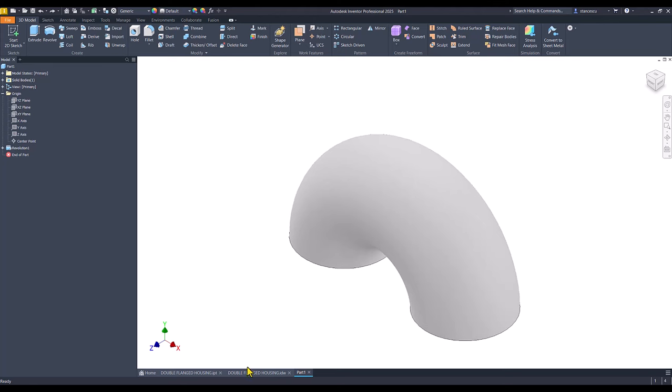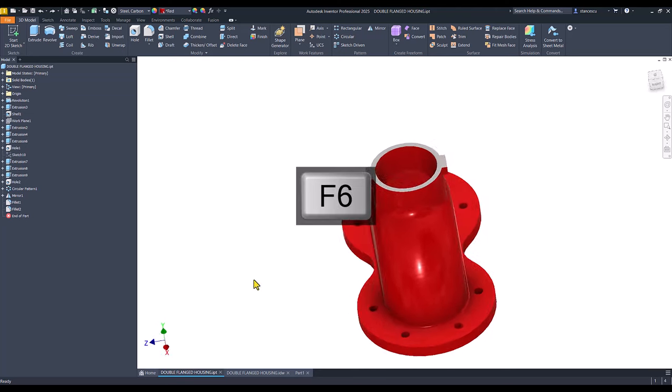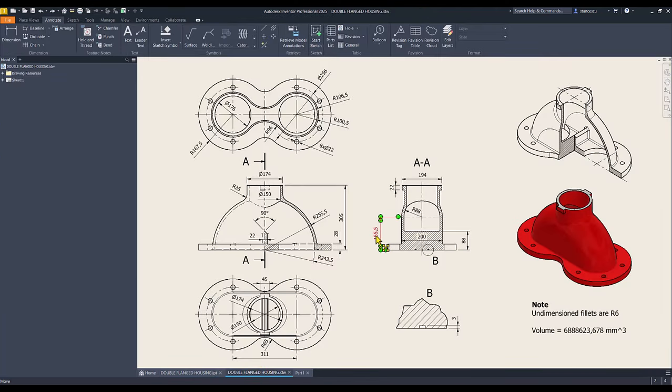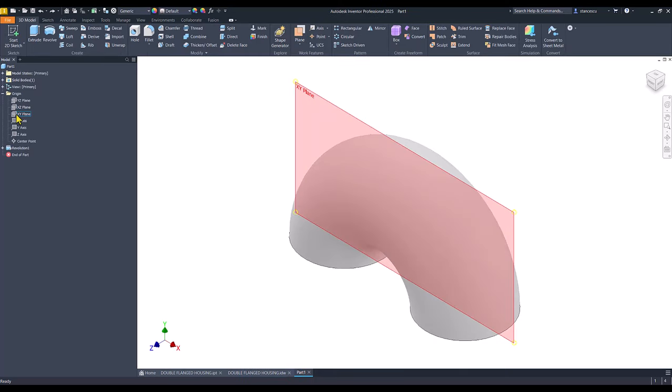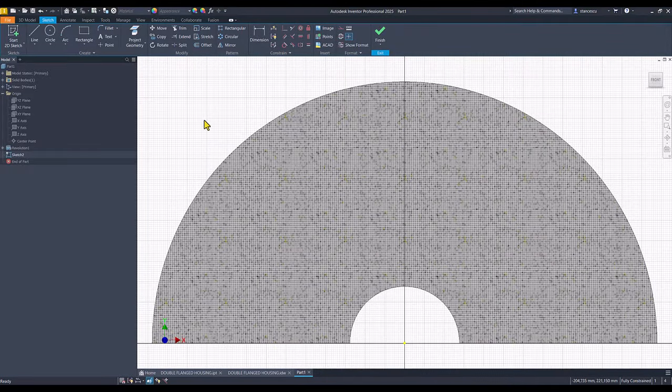Okay, now we have to close these ends by using this radius, and we'll make an extrusion of 200. Let's do this. Plane XY for a new sketch, F7. We draw a circle, center here, with a radius 155.5.